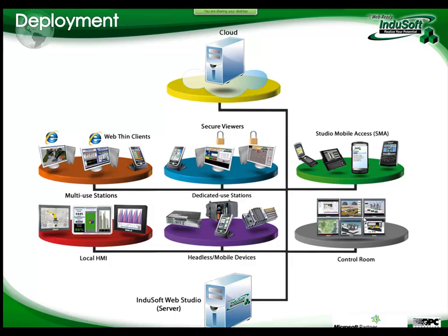Or a control room, with an application, thousands of tags, talking to all the PLCs and all the databases and everything. So you could be running the project in any of these types of devices or architectures, and then you can deploy this data, and the data can be seen by web clients through the network. So you can open an Internet Explorer session and have access to all the screens, all the trending, all the alarm information, everything through a browser.